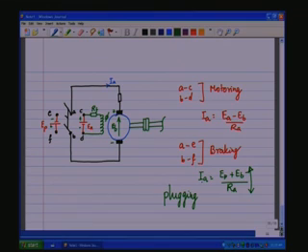The value of IA can be very high, something like 50 to 100 times the rated current. So, the armature windings may or may not be able to handle that. So, it has to be properly designed. Under such cases, one will have to put a series resistance.